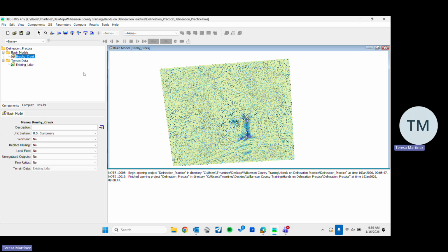But going back to what you brought up, with the survey, shooting the channel, right? That's very crucial when you're doing, let's say, hydraulic modeling, because with LiDAR, if the water is too deep, the LiDAR won't be able to penetrate. So you will see a channel like this because it stops at the water. In that case, we will use the survey information for the channel crossing. So we will go in and adjust the channel profile, the sectional profile.